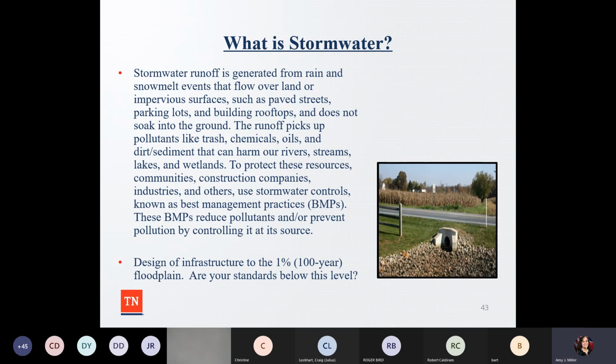And sometimes over time, when you have large subdivisions, maybe the engineer did not design the facilities correctly, or maybe there's adjacent development to that that is causing more flooding in the area. And then it comes down to where citizens are super upset because their properties are flooding and culverts and different things are undersized. So some communities will do a hazard mitigation grant if it's on public property, to revise stormwater facilities.